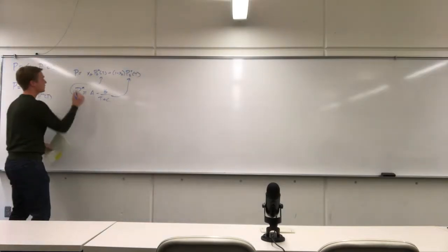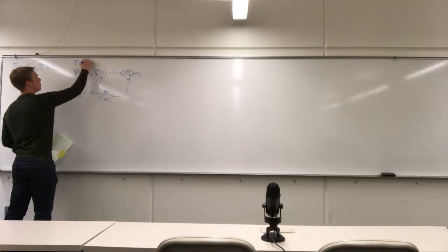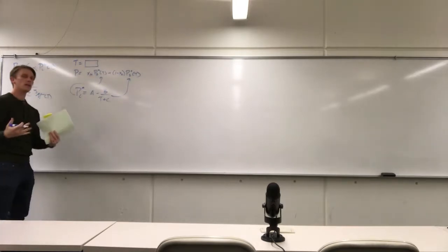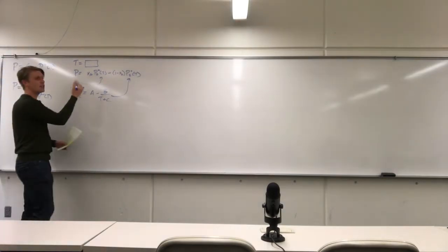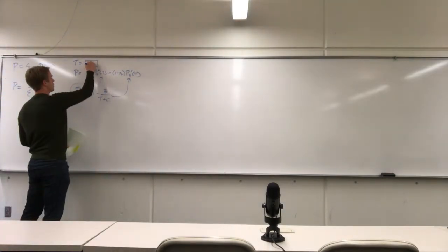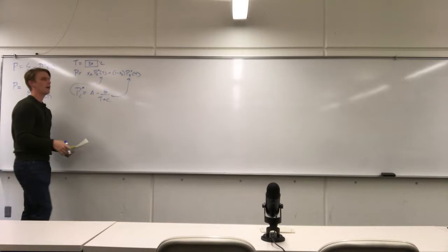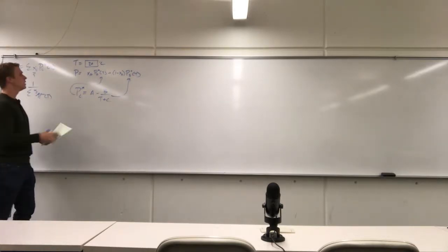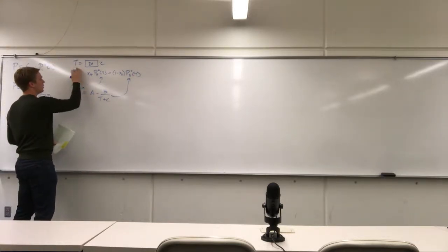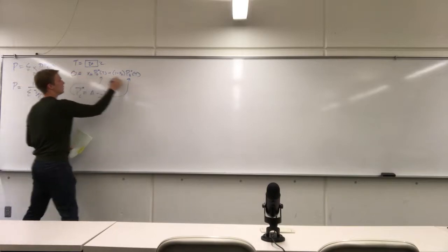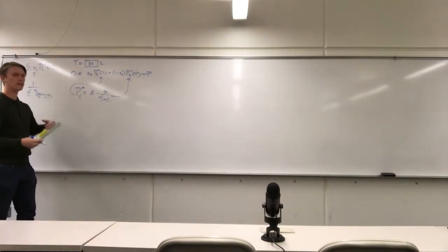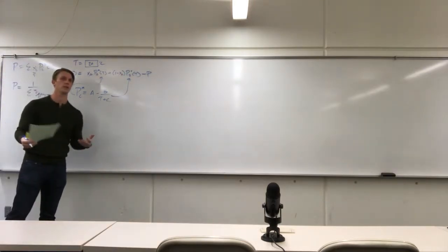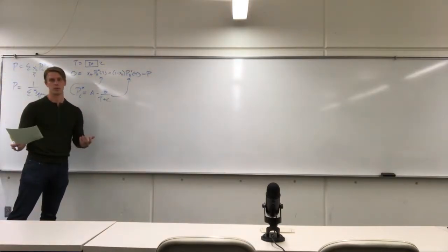So in Excel, I would have temperature equals blank. Now with any nonlinear solver, you have to give it an initial guess. So just throw something out there. As long as it's reasonable, Excel should converge. So let's say 20C. Then just tell Excel, now what I always do here is I move this to the other side of the equation: 0 is equal to this minus P. When this equation is equal to 0, that means you satisfied the one equation, one unknown criteria. You have your temperature of the bubble point.